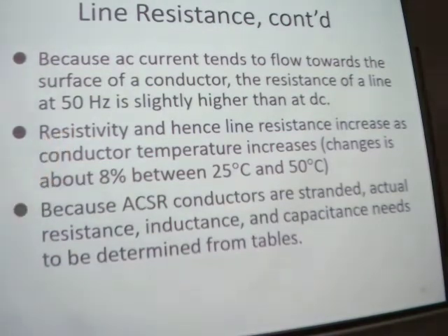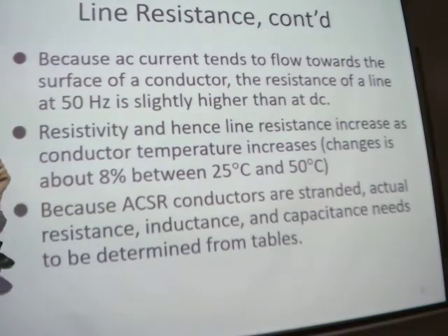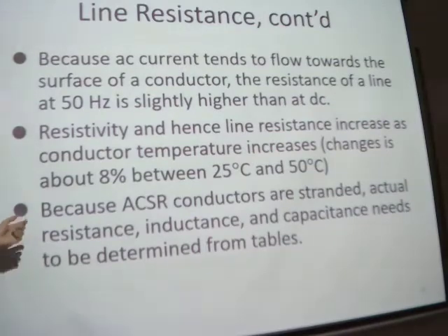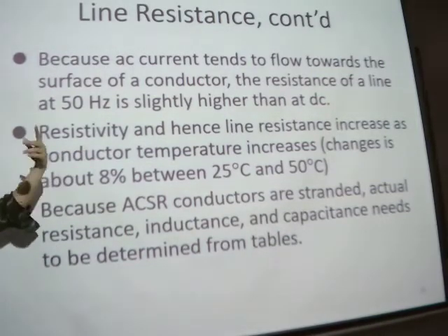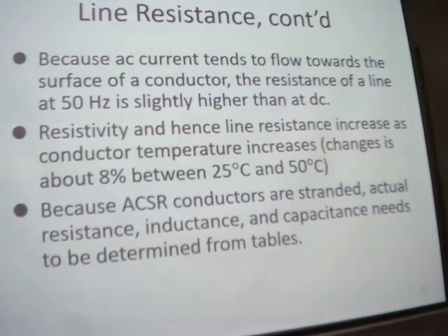We discussed the transmission limitation, that the transmitted power is limited. There is a limitation. We cannot send much more power in one transmission line, because more power means higher temperatures, which also means higher resistivity, and finally much more losses in the transmission network.